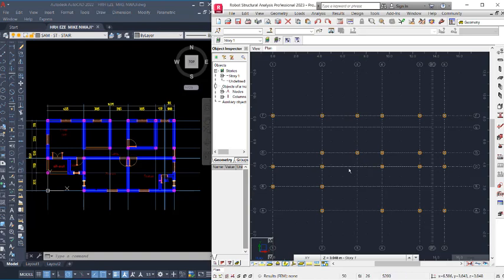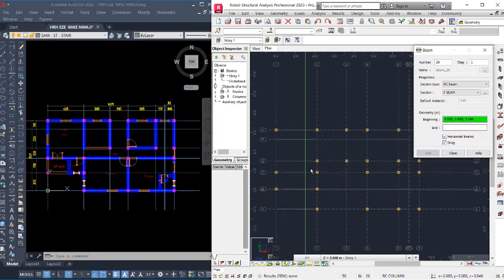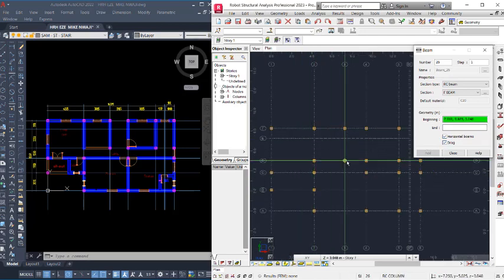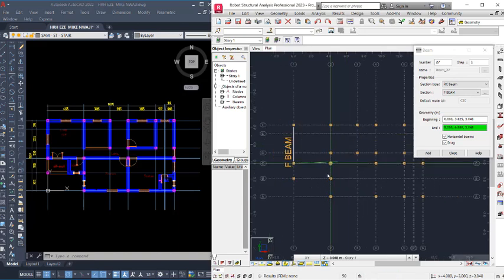So let's make progress with the beams. Right, we want to start drawing the beams. So we click on the beams member right there. Okay, so we will be using RC beams. It is the first floor beam that we will be considering. Right, so we are dragging it. This is going to be a horizontal beam, so we drag it from one point to another. We start from this point, pick that point, pick this. So you have your beam just like that.